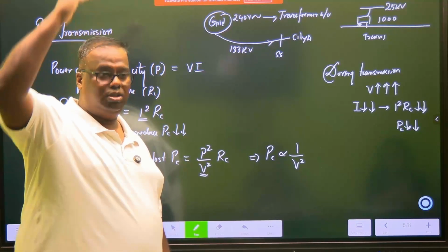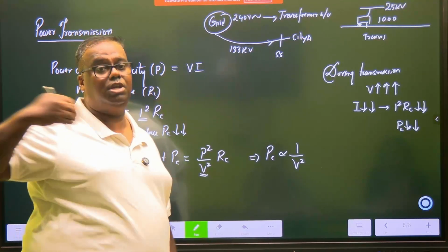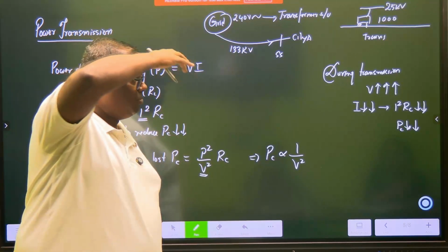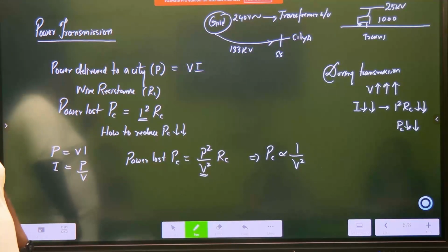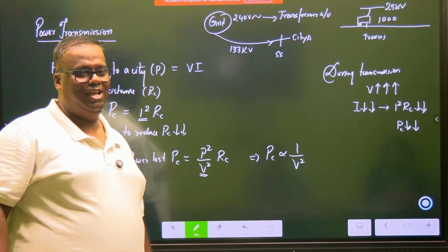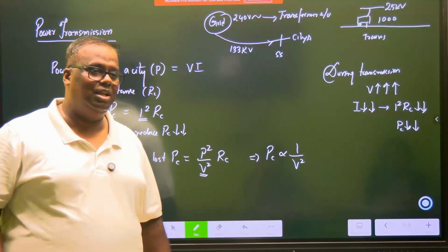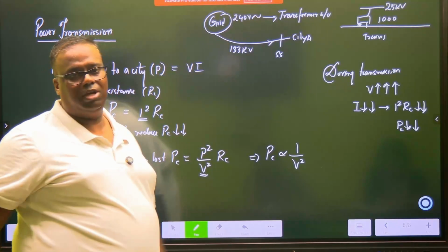No, the engine will step it down. So whenever the railway engine comes, you will see a big noise-making unit. That's the transformer that will step down that 25 kV. Ultimately, the lights that you switch on in your train compartments are only 25 volts DC. So they will convert AC to DC and step it down. But otherwise, long distance transmission becomes a huge issue.